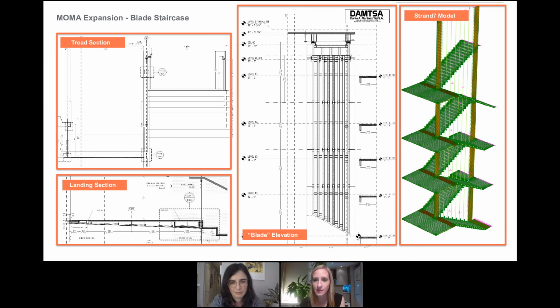But yes, so Byron Harrison asks, what are your recommendations or analysis procedures for dealing with rhythmic forcing, such as dance? As acousticians, we generally aim for stiffness and higher natural frequency to resist motion, but admittedly neglect considerations of overall mass and damping. I think that's a fair approach. The higher the frequency, that's where sort of that 15 hertz is. It's a really high goal. But the higher the frequency, the less potential issues there are to be had.